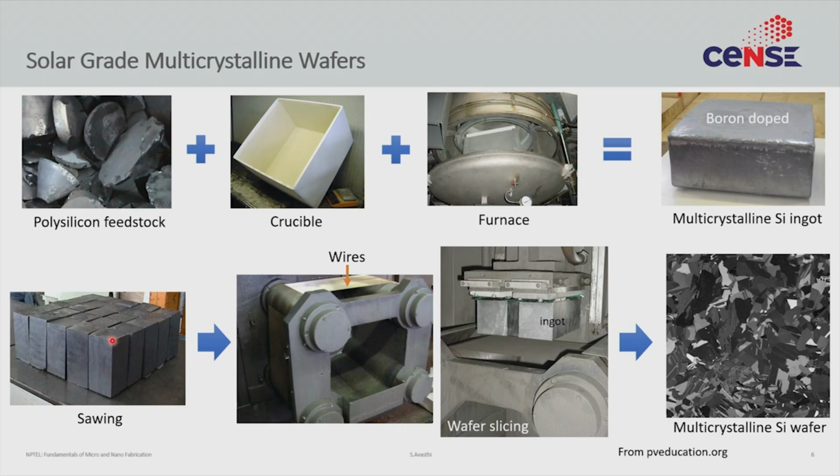Schematically, I think I mentioned this when we were talking about wafering in the first few lectures, but here I'll give you the images of the actual machines. So this is what the machines look like. These are the rollers. You see this shiny part on the top and this taut part on the sides. These are the wires. These are very thin steel wires with impregnated diamond in them. And these very thin wires are what cut these cuboids into wafers.